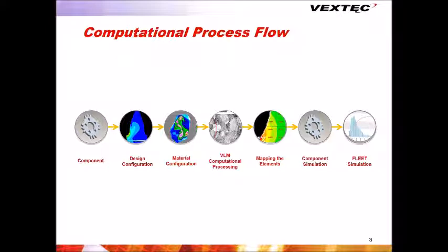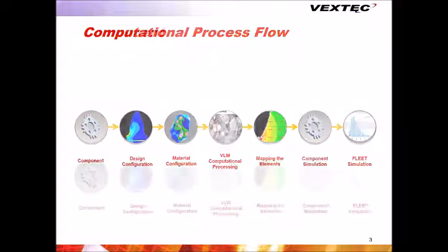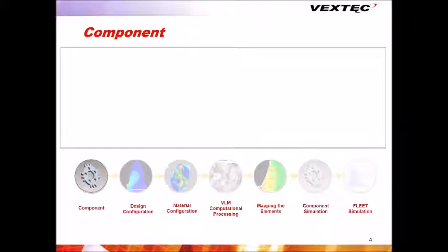The life prediction results are mapped back to the FEA mesh. The life for each FEA element is statistically combined to predict component durability. The entire process is then repeated for all the thousands of units planned for the fleet.